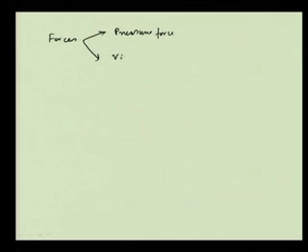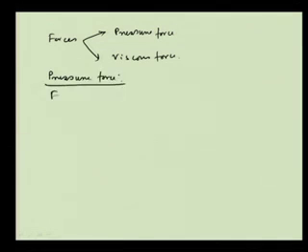We can say the net forces are the pressure force and the viscous force. We have already discussed this part in a different way. Now, for the pressure force on plane 1, it is P into H, with 1 as the area.